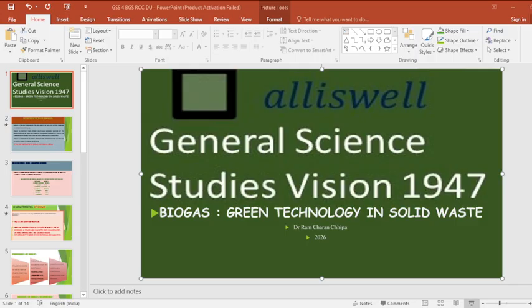So these are the, now here the most one, concealed painting to the reactor in black color is given. Why? Since the bottle is transparent, light will penetrate into it. But if the light penetrate into the bottle, whatever the prototype generation of biogas, algae will be produced, as well as the production of algae leads to development of oxygen which make the bacteria respire aerobically.